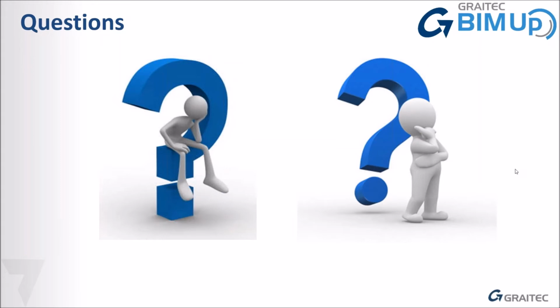I've got a question. You only find these joints when halfway through a large model. How do you get these into your database? Well, what I would do is, if you created one joint manually, like you realize you're in this large model, you've sat there and you've modeled one joint manually, you think, I really need that joint in 14 more places, then I would do a literal straightforward, open a new file, copy and paste via the clipboard. So you copy everything that made up that joint, including the beams that it obviously sits on, into that new file, and then put that new file in that location, the custom connections folder, and it will be available then to reuse as often as you like. And you can just use that insert like I did.